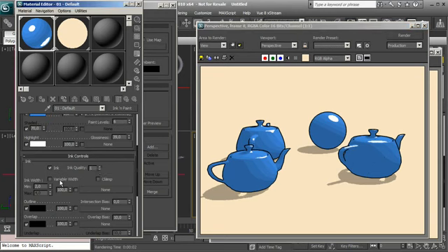Let's go there, and we have the variable width. So we have the possibility to have some areas with a higher width for the ink paint. Let's try with 8, and you can see better on the sphere. So you see this area very big and a thinner area. Let's use fewer layers for the paint. Okay, and we have the possibility to use a texture and to decide how much of the texture must be used.